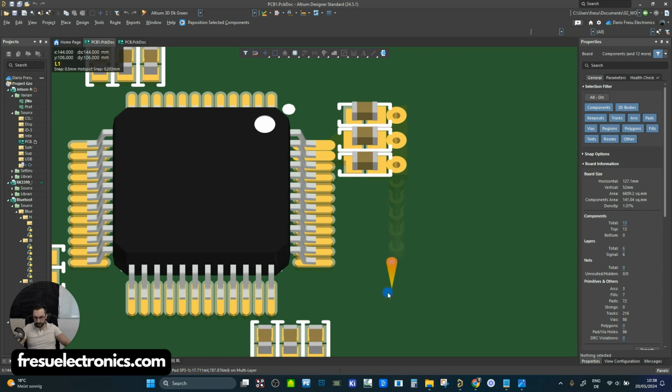But the other problem that we have to mention is that if we place these capacitors farther away, then we will also have this part of the connection, where we can couple some noise from the other traces routed across these points. And then this noise can couple to the power delivery network. And once it couples to the power delivery network, it can reach through the whole network. It can reach other ICs, and these ICs can also be connected to cables, and then these cables will radiate at certain frequencies.